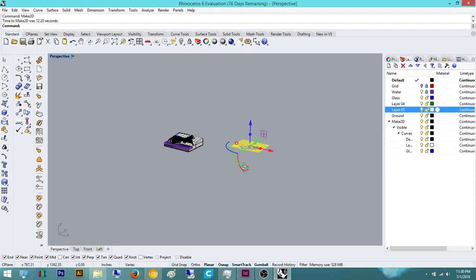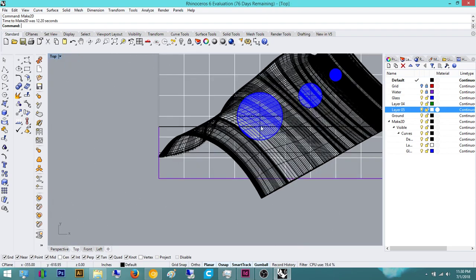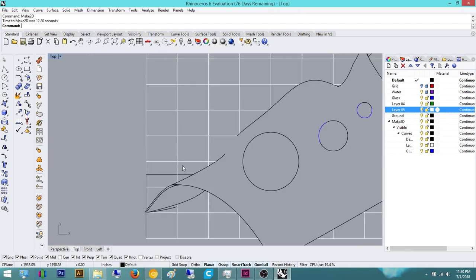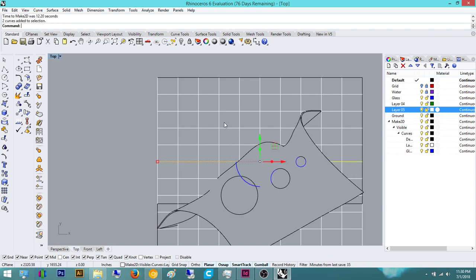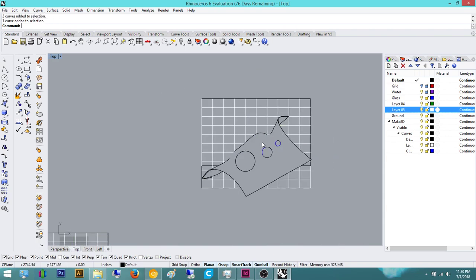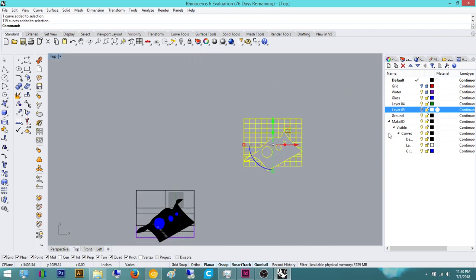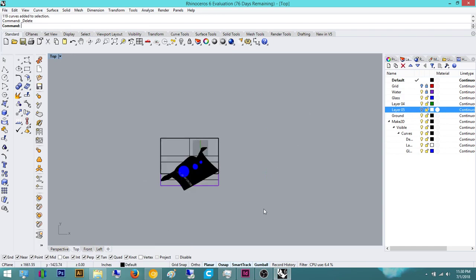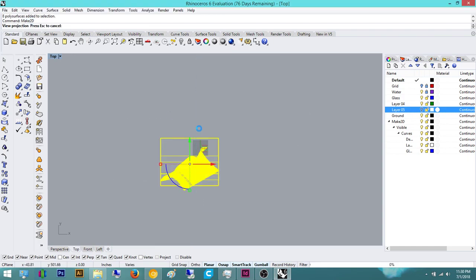And now we can check out our drawings. So you can see this is not a very detailed drawing, but it's a start. So we can now have some geometry to work with. I would probably not use these. Maybe I should. Let me try turning off the white curves. Delete this and do another Make2D. Let's do another one.